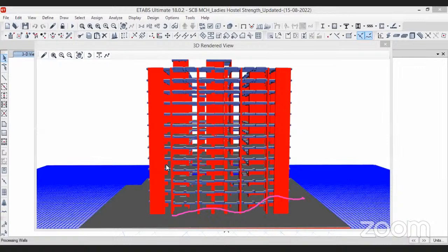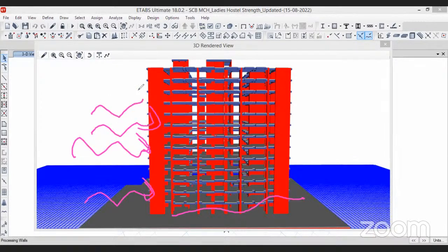Hyderabad is under seismic zone 2. If you're designing buildings under higher locations where the seismic zone intensity is more than 2, then the reinforcement for every floor's beams will change, because you have a predominant lateral force hitting your building. This lateral force will change, but for the slab it is only a limitation on the load. Slab is only a media. It will not take the load, it will distribute the load.